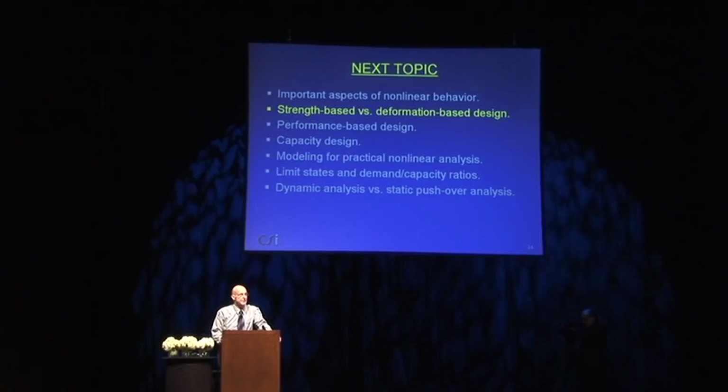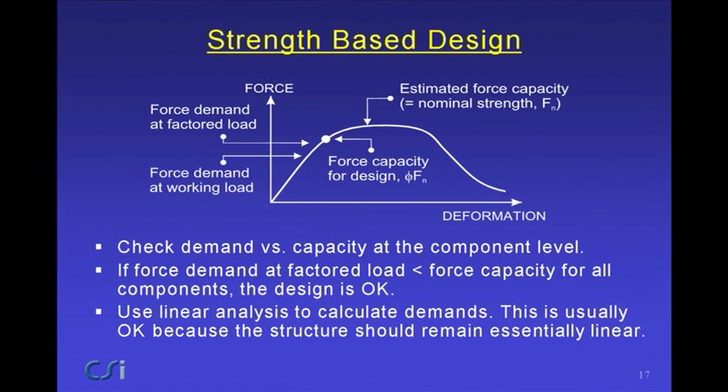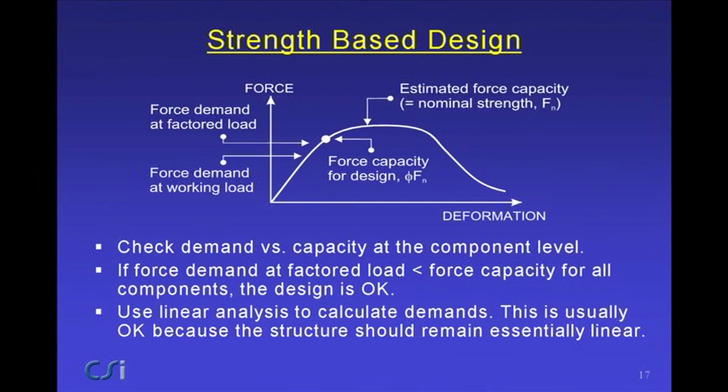So the second topic is, let's look briefly at strength-based versus deformation-based design. Strength-based design first. Again, this is the force-deformation relationship for a typical component. There's going to be some estimated force capacity, typically the nominal strength. You may apply a phi factor to get some usable force capacity for design. That's on the capacity side. On the demand side, you could calculate the force demand at working load somewhere here, apply a load factor to get the force demand at the factored load.